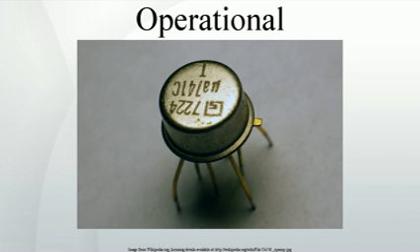Input impedance. Because Q1 and Q3, resp. Q2 and Q4, form a Darlington pair, the small signal differential input impedance is of order 2 hFE hie, where hie is the small signal input impedance, common emitter, of Q1 and Q3, resp. Q2 and Q4, and where hFE is the transistor small signal current gain, or beta. This contrasts with what would be the case with a simpler emitter-coupled pair, long-tailed pair, input stage, where the differential input impedance is a factor of beta lower. A typical 741 op-amp has an input impedance of 2 to 8 MΩ.